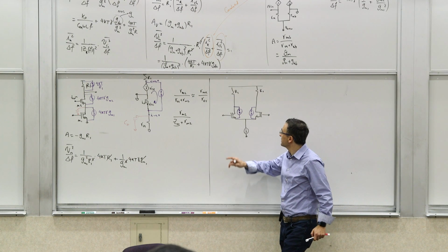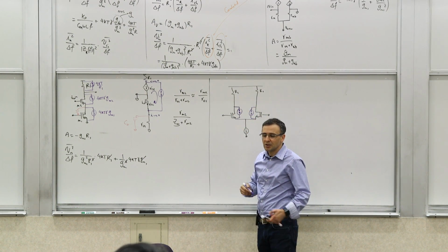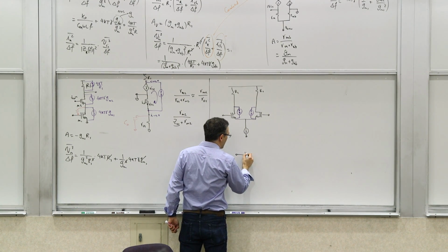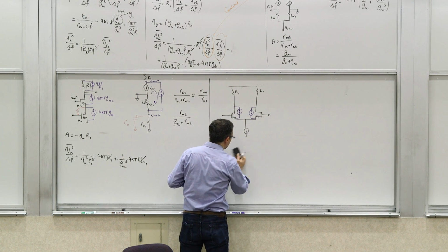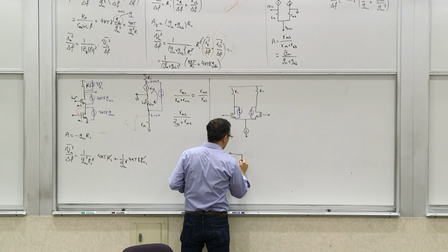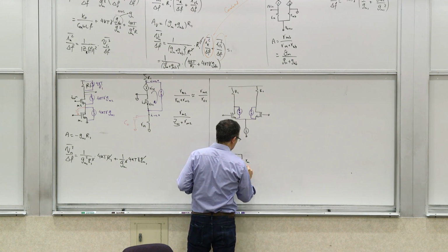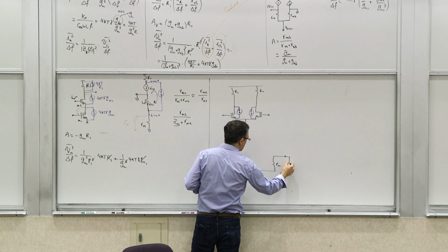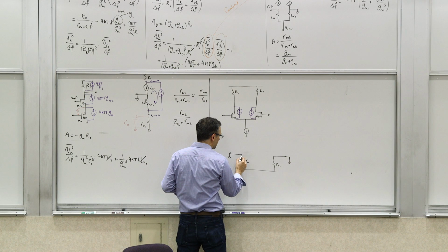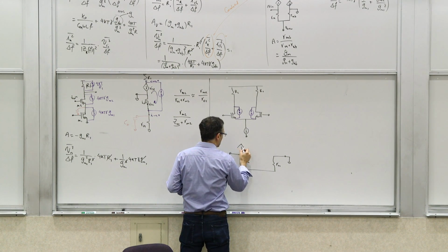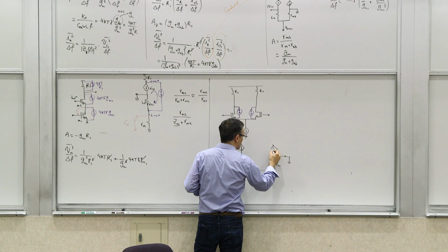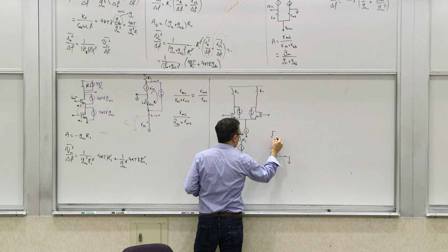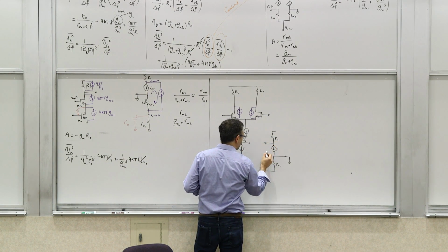Well, you were trying to calculate the transfer function from a current here to the output, right? There are different ways to think about it. One way to think about it is from a small signal perspective. If you think about it from a small signal perspective, this is what you have. You have Rm here, and then you have Rm here, right? If this is grounded, and this is grounded in this case too, there is a current source here, and then you have R1 and R1. And this is your differential output.